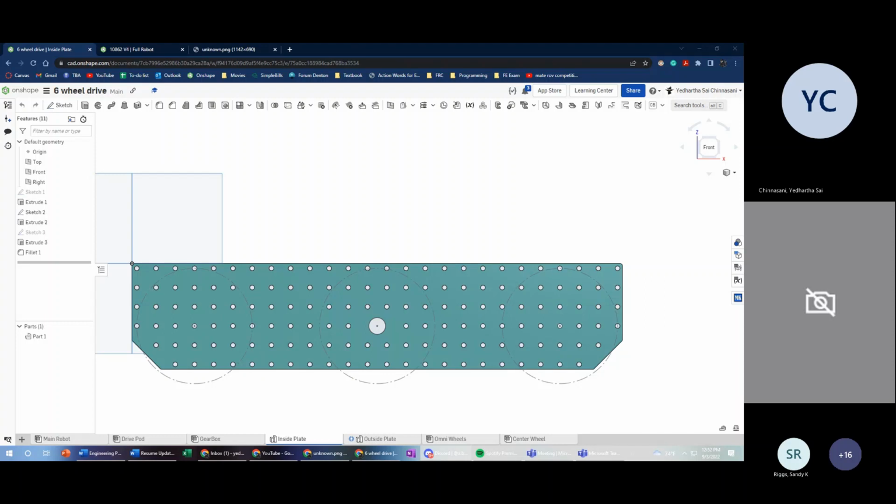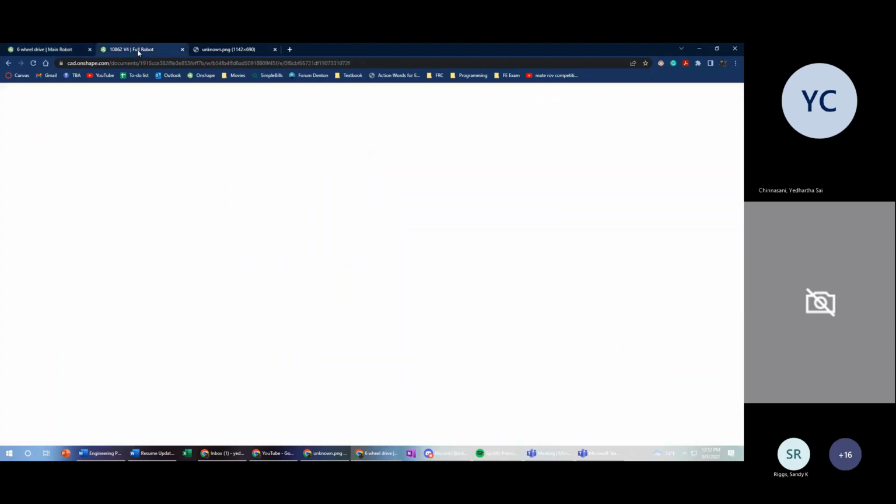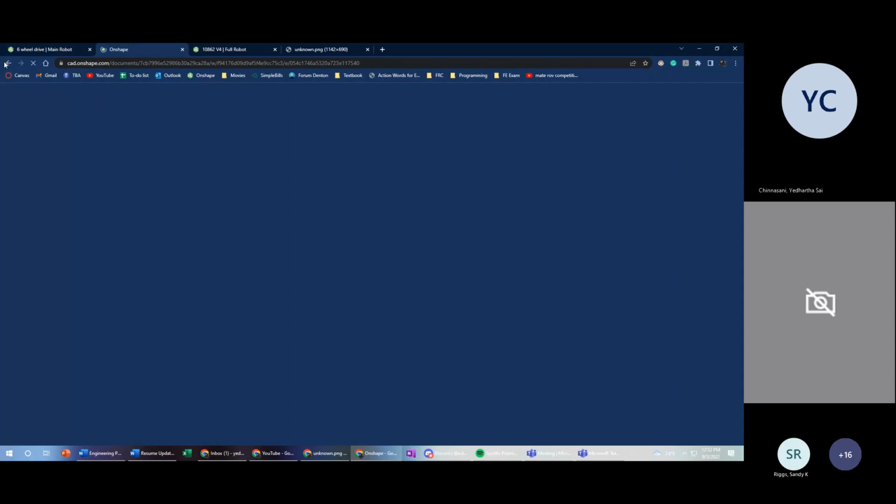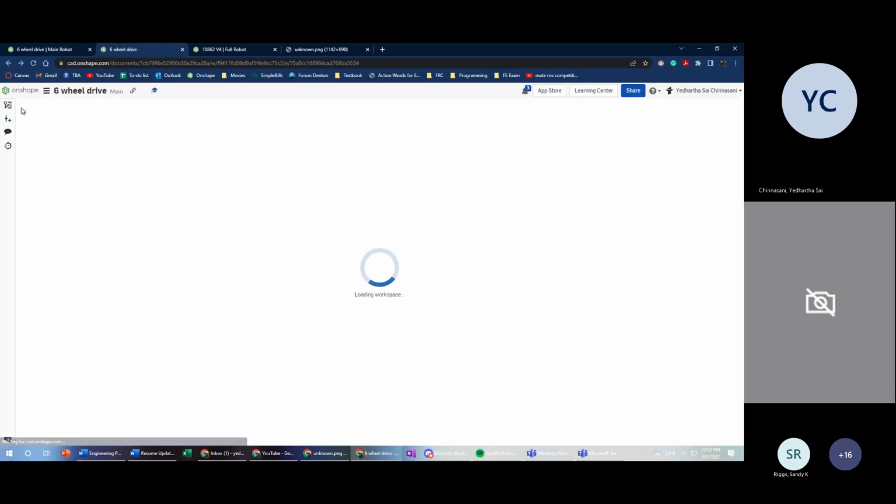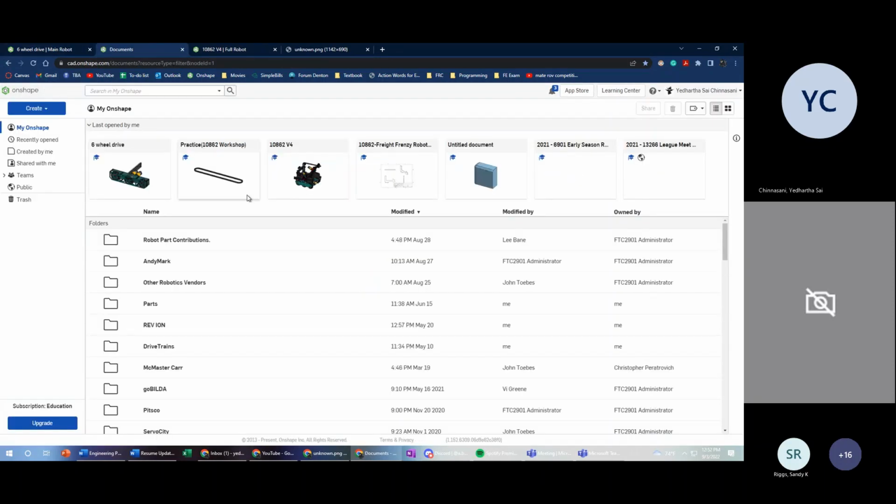Making sure that you're dimensioning things to fixed points, to lines that are not really going to be manipulated that much, is really important. So I would really emphasize thinking about having your lines dimensioned to points that you know aren't going to move. So maybe that's the length and the width, or lines that won't be changed that much. That's really important. That was just one thing I wanted to add.